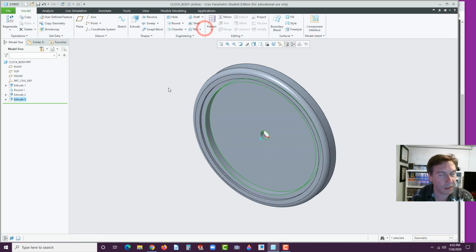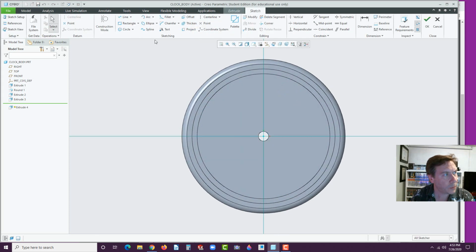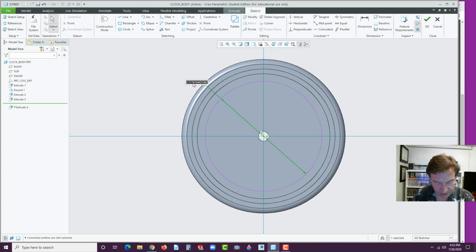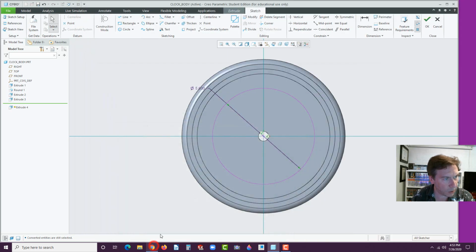It's mathematical. All right, now select this face, go to extrude, draw in the bolt circle, so go to circle, draw out that circle like that, then click on it, and right here you could change it, construction. That way it's innocuous, and this is supposed to be 5 inches, let's just verify that on the print. And there it is, so we're good to go.